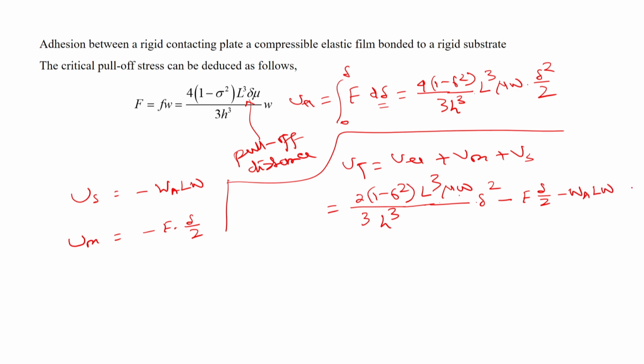So this is the total energy of this particular film, and see here L is a parameter, the length, a spatial dimension. We need to minimize this energy, we need to see what is the minimum amount of energy that needs to be applied with respect to L. Therefore del U_T by del L we have to set equal to 0.